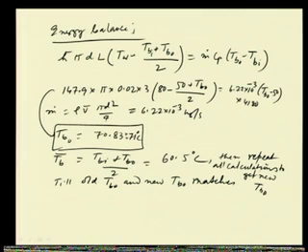Repeating all calculations means we have to get all the fluid properties at T_b bar, then repeat the calculations, get the new T_bO, and continue the work till the old T_bO and new T_bO match.